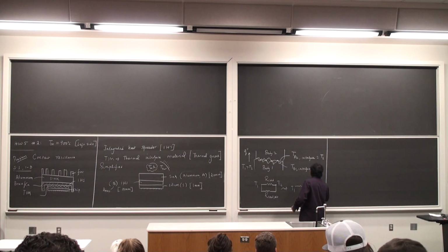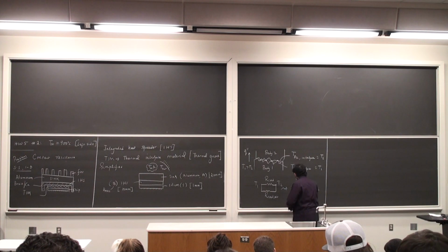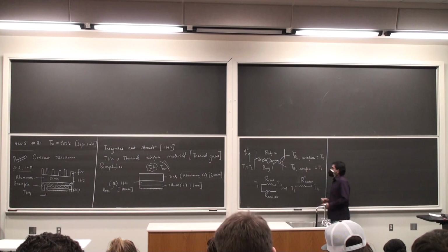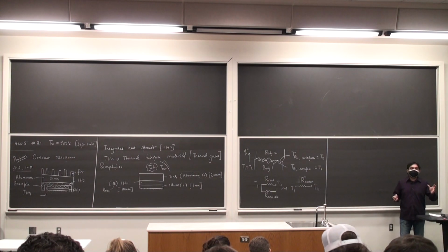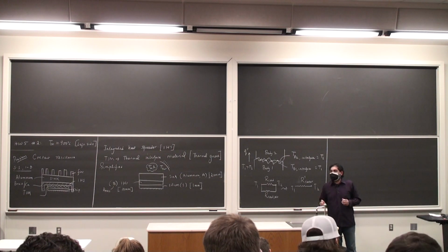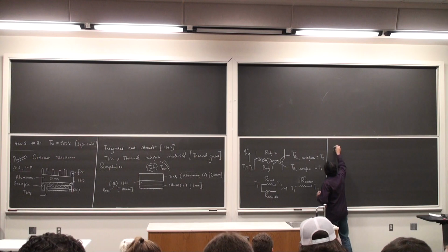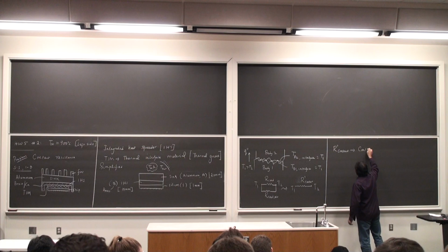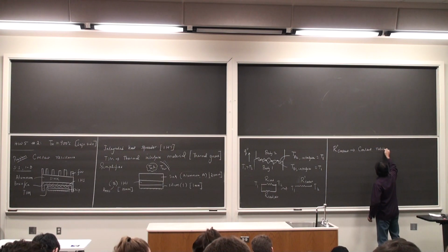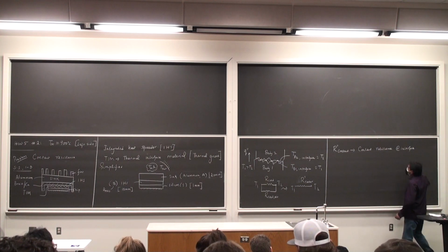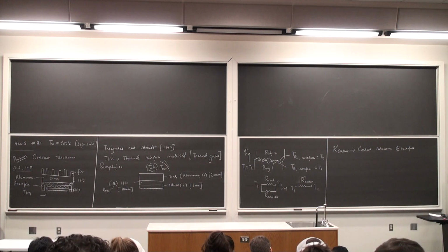T1, T2. This is R double prime contact. So R double prime contact is some kind of an empirical value of the contact resistance for some area that you use in the experiments. Okay? So R double prime contact is the contact resistance at the interface, which symbolizes the fact that there is a temperature gradient at the interface.